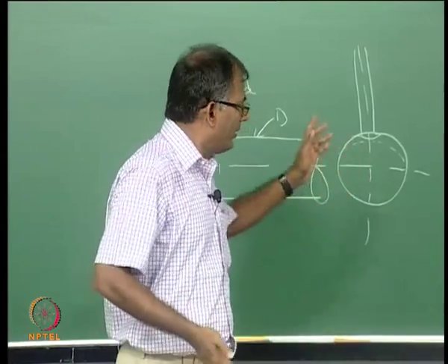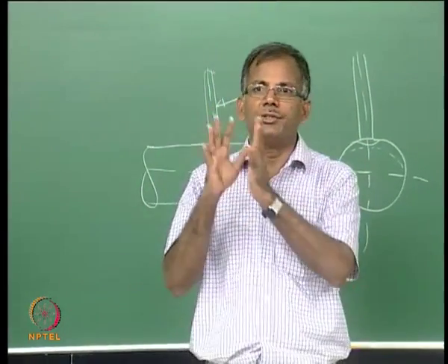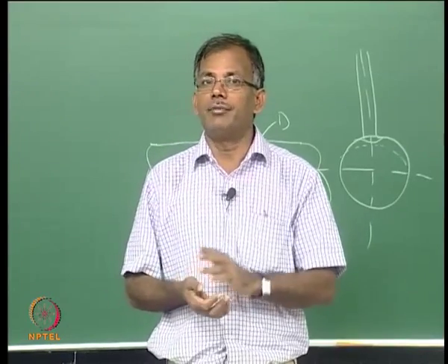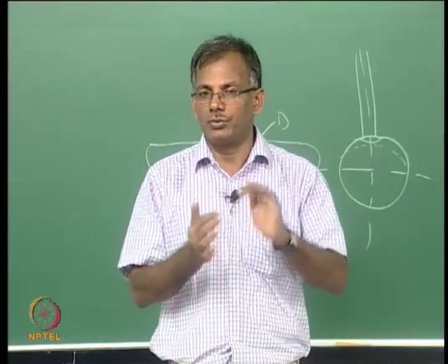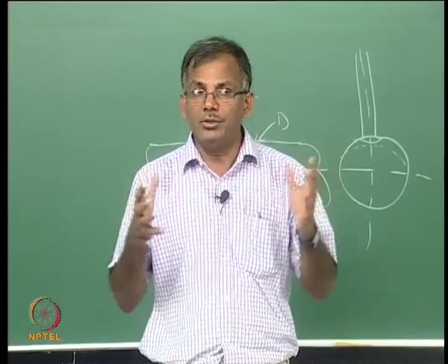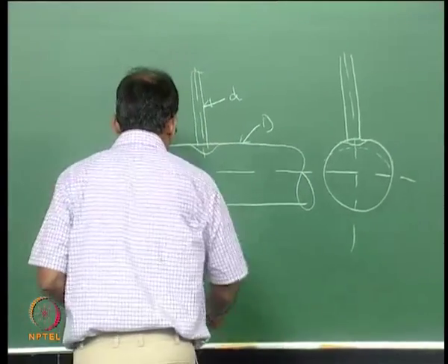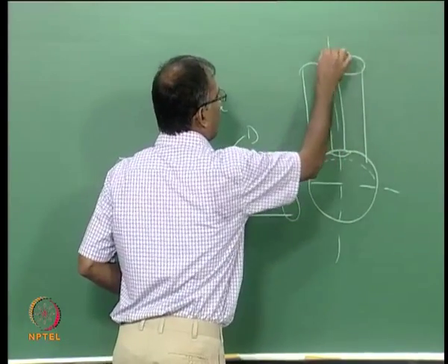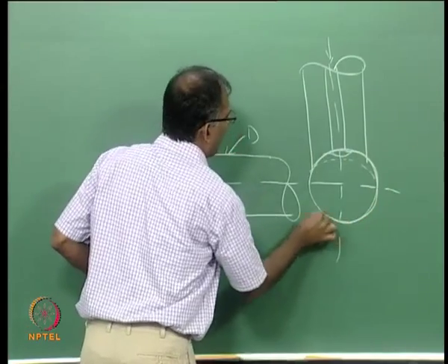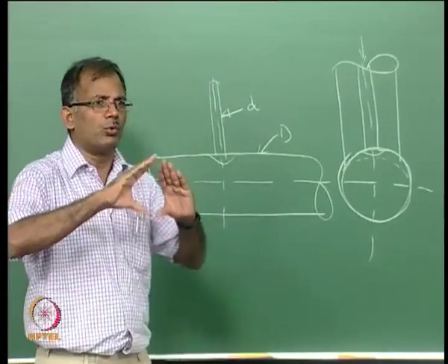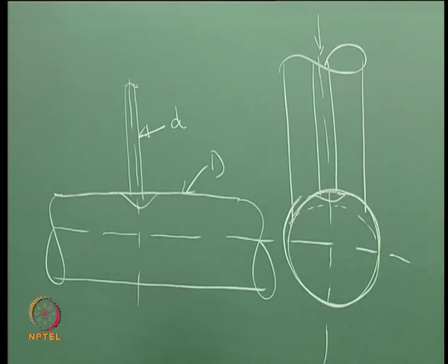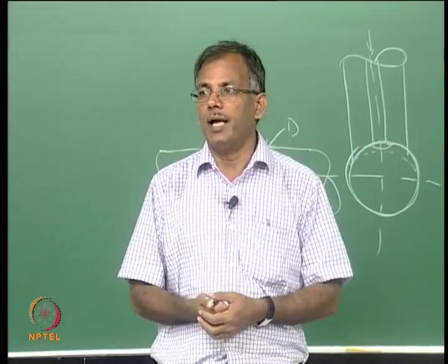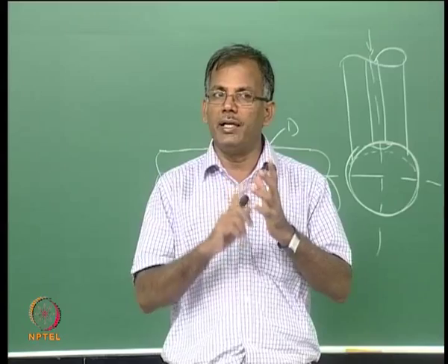So one behavior is when the diameter ratio is small, the failure pattern, the load at which the connection will fail, is going to be different. When the diameter ratio is made bigger, you just go to the same picture, you make it somewhere here. If you put load again, the pattern of failure is slightly different, because this is going to ovalize the pipe, because the distribution is larger, taking into account the larger length of the pipe. So you could easily now understand why they have selected the diameter ratio as one of the important parameters, because the failure pattern is going to change.